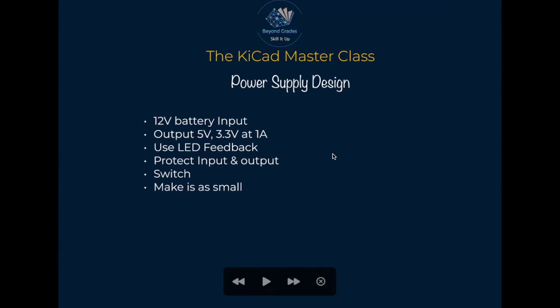And you realize that I want to capture everything that we've gone through so far. Like when I say we need to use some feedbacks, we're using some LEDs there. For us to get the 5V output, it means that we need now to use voltage regulators. We have mentioned this when we were dealing with ICs, and it's pretty easy to identify these ICs. Just like I was saying, it's a matter of going to the vendors themselves, searching for an IC that can give us 5V and maybe 3.3V. We can use 2 or 1, it depends.